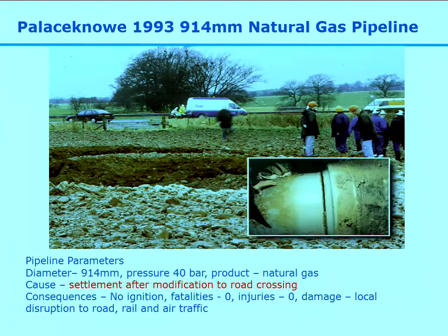Sorry, question. How do you classify this kind of failures? Well, this one is classified as other because there were three main causes of the failure. One was it had been modified on site, and the backfill, which had been placed under the pipe following the machining and welding, was not properly consolidated, so basically the pipe wasn't properly supported. There was a lot of loading over the pipe once the road had been constructed over it, and then there was the problem with the weld procedure.